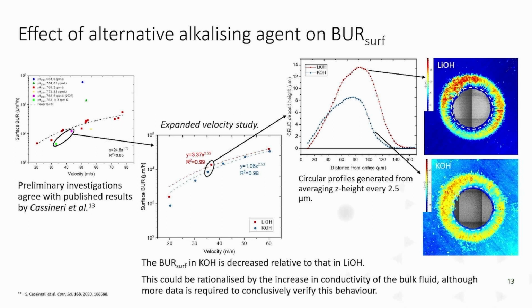So what we could be doing here is negating the need or promoting the back conduction to the fluid of this excess in charge and reducing the extent of the wall current that drives this oxidation and the deposition formation. But this is very much a work in progress. There's more data points to be added, so it's a watch this space for this sort of study.